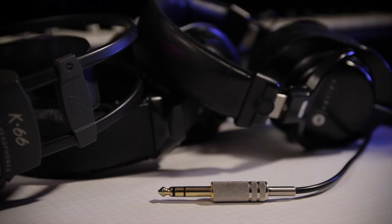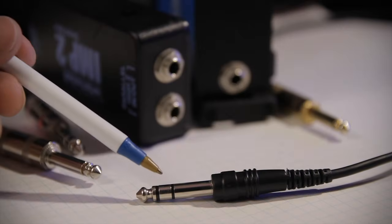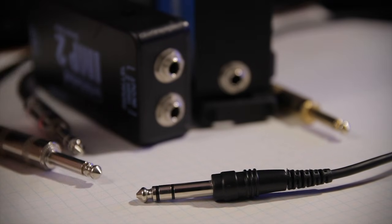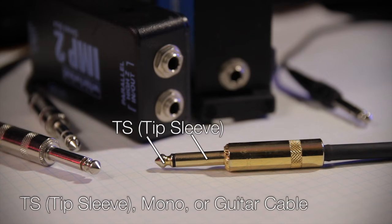This connection has many uses. For example, professional headphones use this connector, and it carries the signal as left, right, and ground. On balanced outputs of a device, this would be positive, negative, and ground. There are also mono or TS versions of this cable, which you may know as a guitar cable. These are the same size, but only have a tip and a sleeve. Some pro audio speakers use the same 1/4-inch TS connector, but speaker cables are not the same as instrument or line level cables and shouldn't be interchanged. There is more to TRS cables and connections, but these are the basics.